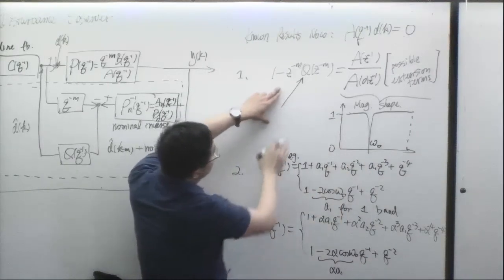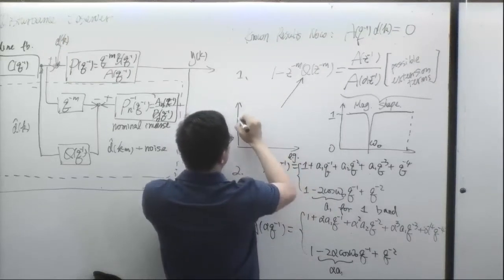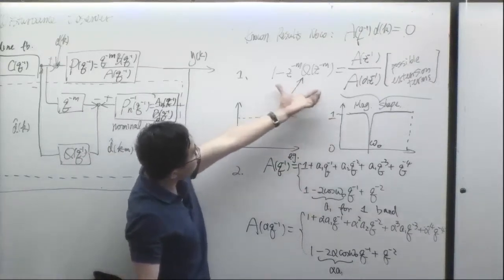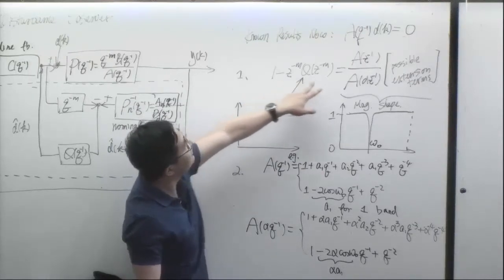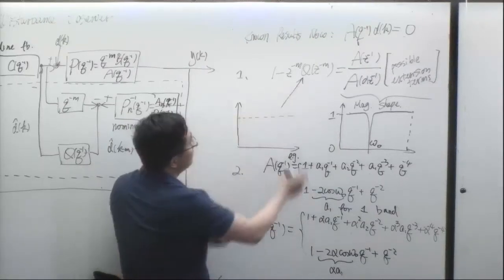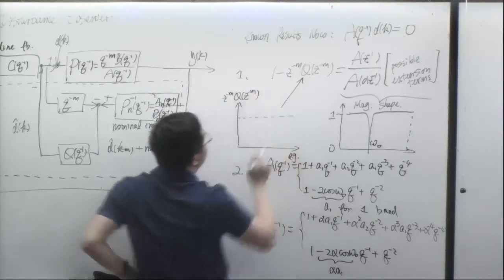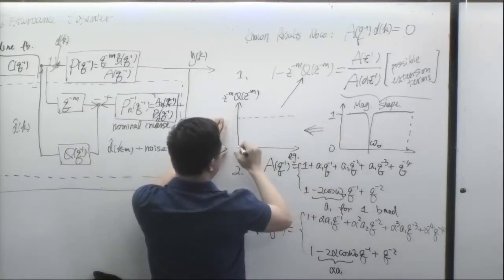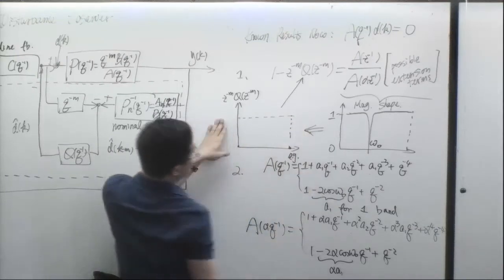So we can do the analysis over here again. If this entire term is 1 at low frequency, that means this part at low frequency, the magnitude should be approximately 0, right? So I know the magnitude response of this filter should be, because of this design over here, pretty small at low frequencies. It is also pretty small at high frequencies.